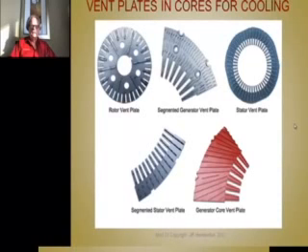In some of the earlier slides, I discussed several times the ventilation plates that are used in cores to provide cooling passages. And here's some nice close-up pictures of some of these. Here's a ventilation plate used on a rotor of a motor, probably an induction machine. And here's a segmented plate for a synchronous generator with open slots.